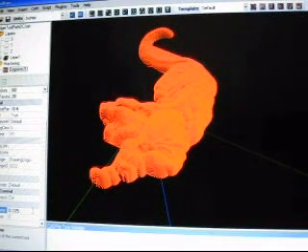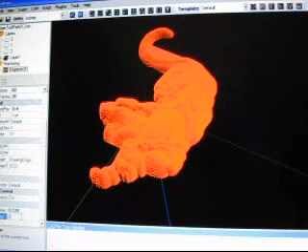So I can put a tool diameter in it. It doesn't matter. An engraving program is going to run on the line with the center of the tool on the line no matter what you do. So the only reason why I'm putting tool information into this program, and I'm going to number it, is that I'm going to put a tool number on it.